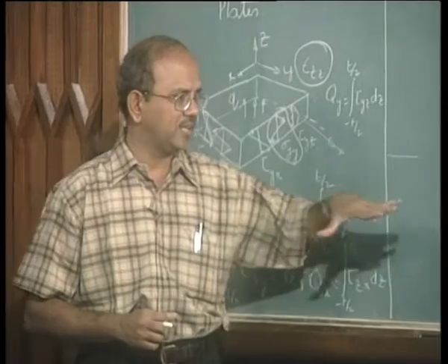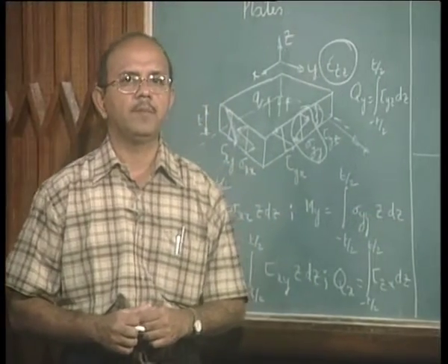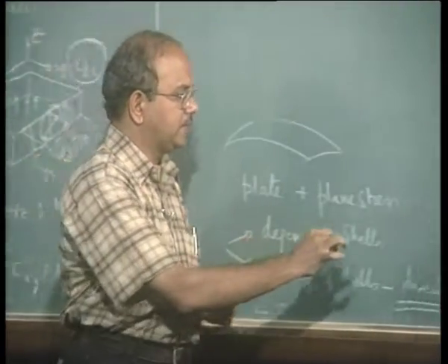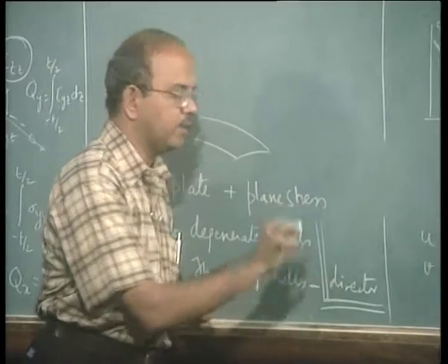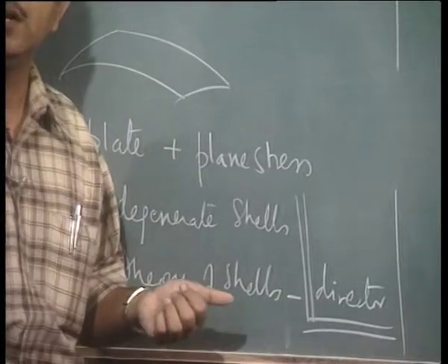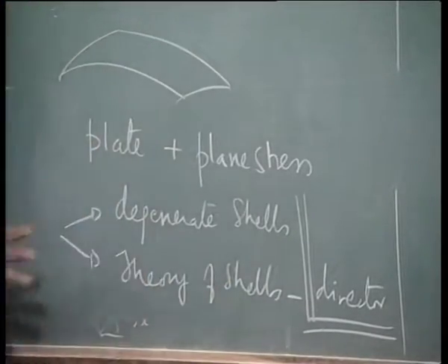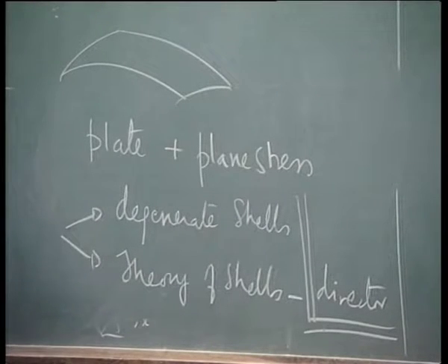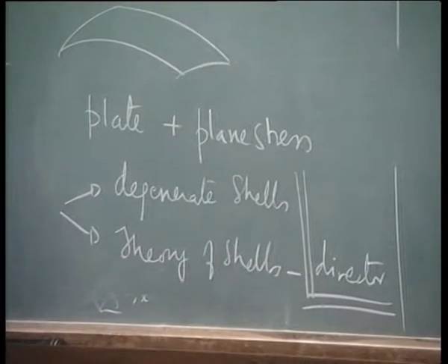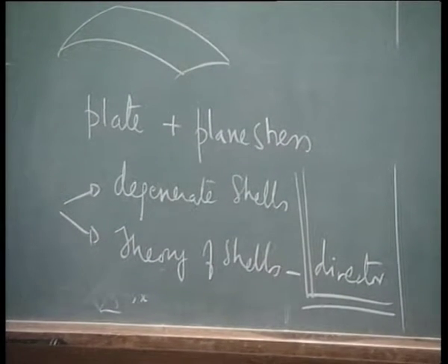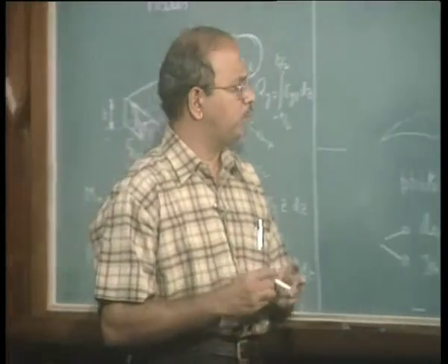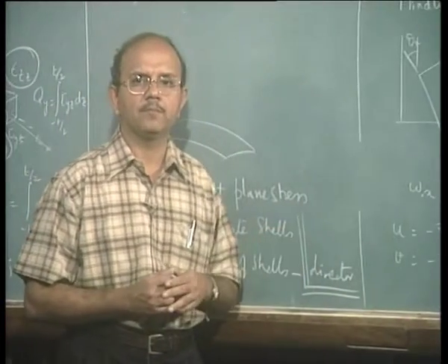The last word is still not yet said about the shells, but it is important to realize, when you use a package, what it is based on, and maybe it will be a good thing to do a few examples for shells in order to understand how shell elements work. In fact, I would say that a real test of a good software is to look at shells.